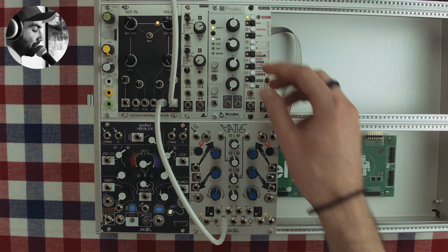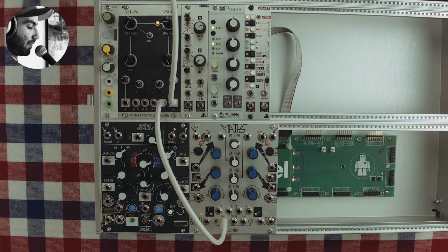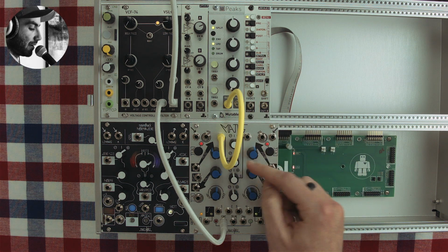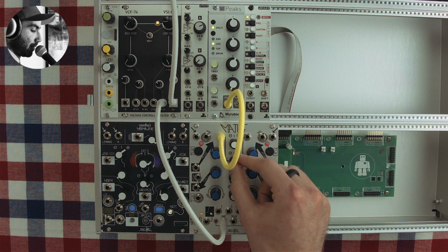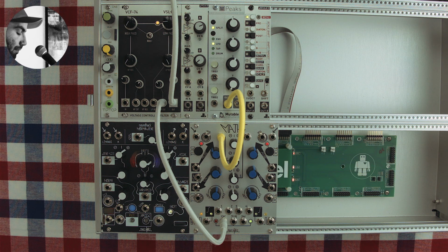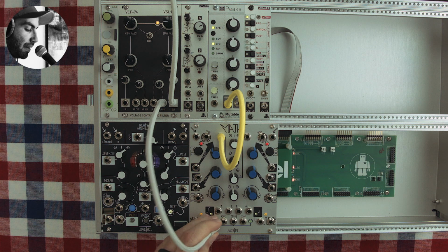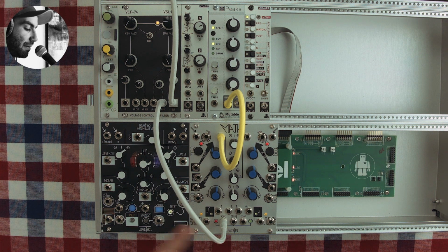But for example, if I turn this back to an LFO, if I patch this square wave LFO into channel 2, I can add a bit of channel 2 now. As you can hear, the OR gives me the maximum value, so when the gate is high here, it'll grab one of the other ones, and then when it goes low, the other one becomes higher, so it chooses that one instead.